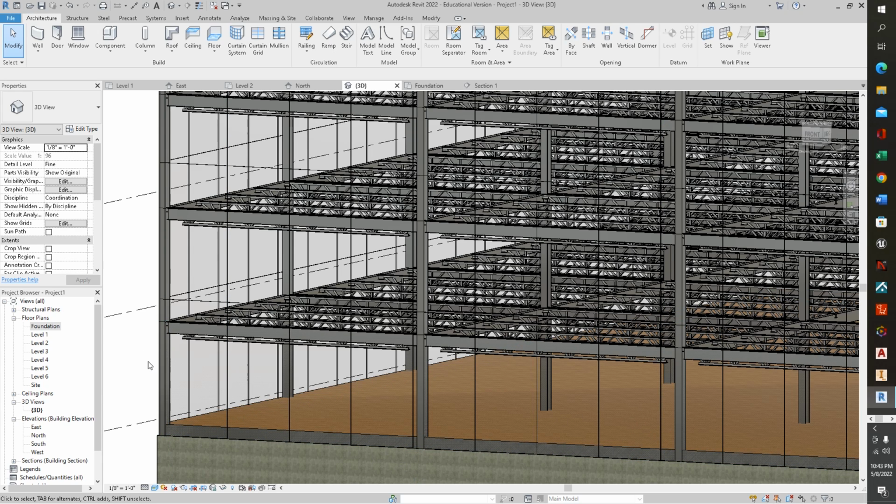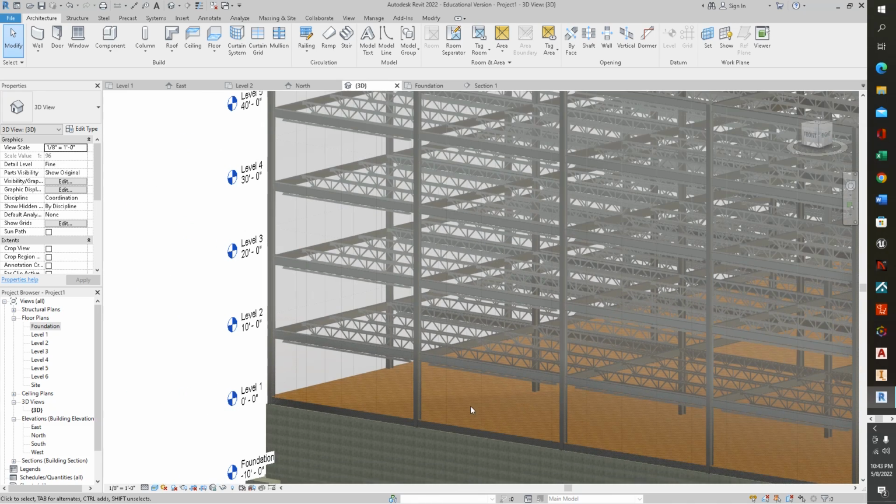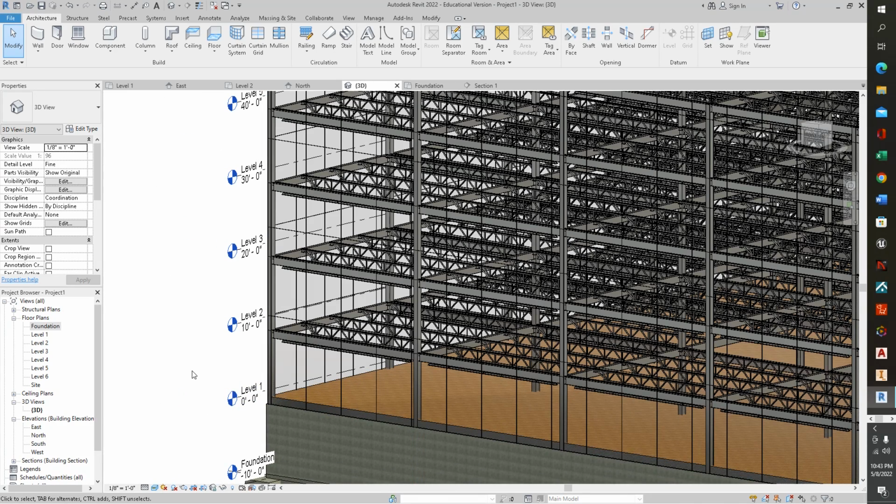Oh, however, that makes it so that we have to remember when we're adding in doors and features that those need to have an offset of 12 inches, or else you'll have doors that start a foot deep into your floor system, which obviously won't work very well if you're trying to open a door and it's sunk a foot deep into the concrete that you've poured. It's just not a good practice. Your people are going to get a little bit upset at that.